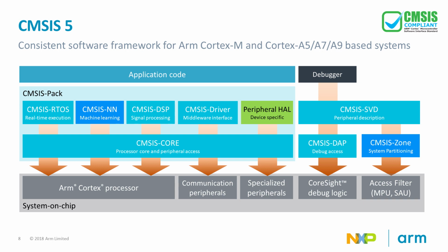So what is CMSIS-NN? CMSIS-NN, as in neural networks, is the latest addition to CMSIS. CMSIS-NN is a software component that contains efficient kernels developed to maximize the performance and minimize the memory footprint of neural network applications on ARM Cortex-M processors targeted for intelligent IoT edge devices. It utilizes existing CMSIS components like the CMSIS DSP library and CMSIS core for simple and optimized deployment on all ARM-based microcontroller devices on the market.